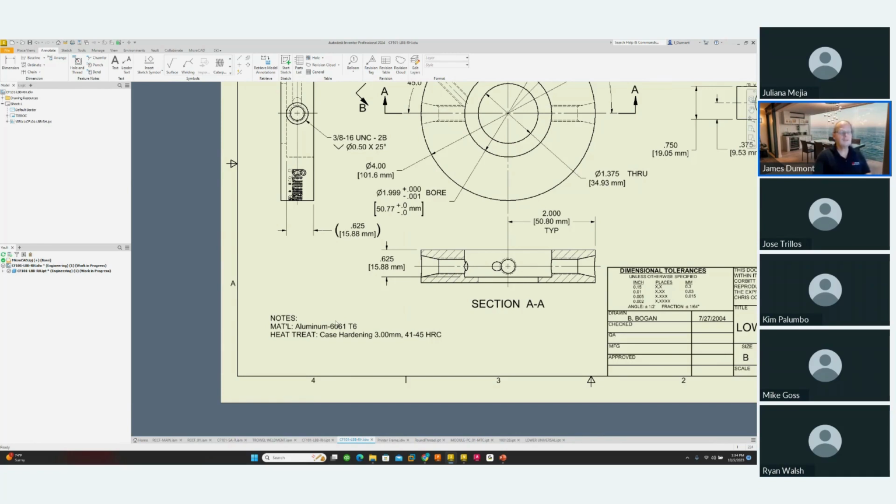But what you can use it for: we've got a lighting manufacturer doing this whole automation. They're doing iLogic, engineer to order, and ERP integration. One of the things they need is they powder coat a lot of their product. For costing, they need surface area, and they know how thick the powder is. Now they can actually cost how much powder they need to paint each part.